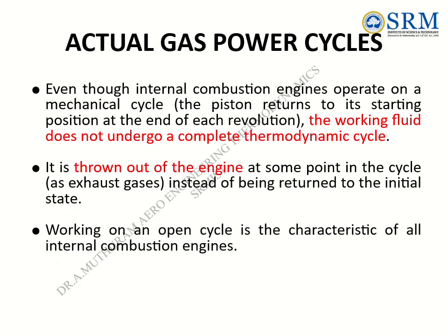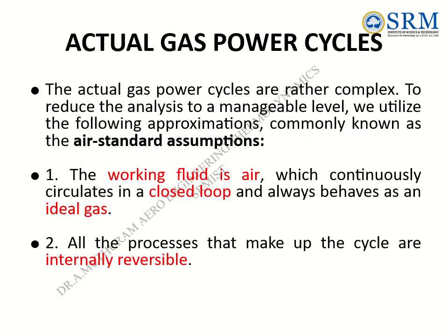Even though internal combustion engines operate on a mechanical cycle, the piston returns to its starting position at the end of each revolution. The working fluid does not undergo a complete thermodynamic cycle. It is thrown out of the engine at some point in the cycle, as exhaust gases, instead of being returned to the initial state. Working on an open cycle is the characteristic of all internal combustion engines. The actual gas power cycles are rather complex. To reduce the analysis to a manageable level, we utilize the following approximations, commonly known as the air standard assumptions.